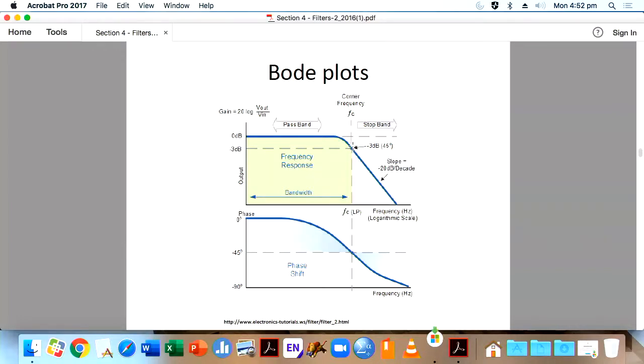This is for a low pass filter, and this is the pass band, meaning all the frequencies are passed through, and then this is the stop band. See, the stop band is ending here. This much frequency is still going into your circuit, because you got this big slope. If you can design one that comes straight down from here to here, that is the ideal filter. You won't be able to design it. So you will always have some kind of slope, and because of that region, some frequency components, this much, are going into your circuit.